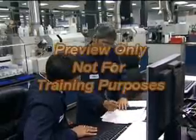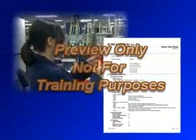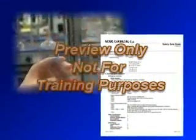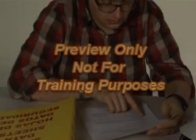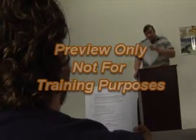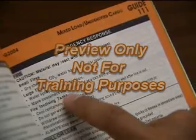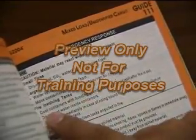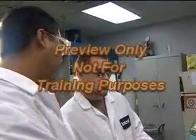The list of hazardous chemicals should be cross-referenced with the safety data sheets to ensure the list and the safety data sheets are accurate and correctly reflect the number of hazardous chemicals in the workplace. Hazard information must be communicated to employees. Employers must establish and implement a written hazard communication program covering the list of chemicals, use of labels, safety data sheets, and employee training. This program should outline the different policies and procedures the employer has in place to keep employees safe and ensure adherence to the HCS.